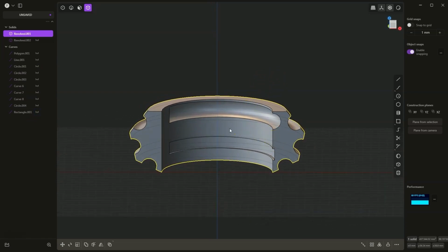So as you can see, using the revolve operation, we can create a solid, and then if we need to, we can create another solid, and we can use the Boolean operation to subtract one solid from another solid. This is another basic operation useful in creating 3D models.